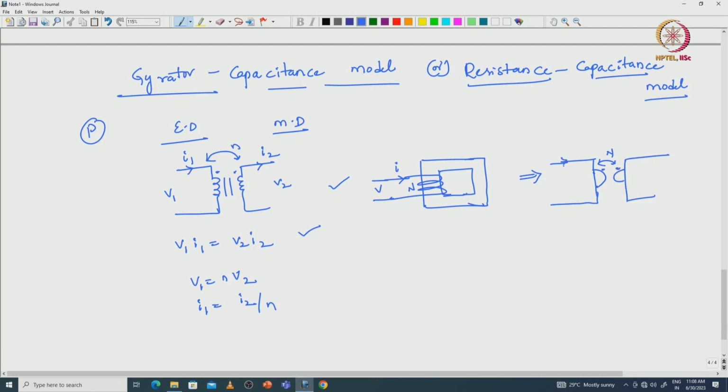The flow variable at the primary side is current, where current is equal to the rate of change of charge, dq by dt, and the effort variable is voltage. The effort variable at the secondary or magnetic side will be mmf, and the flow variable is d phi by dt. We can represent this variable as Im. Im is equal to d phi by dt, not the flux. So, both side flow variables and effort variables are defined with respect to the Gyrator model.